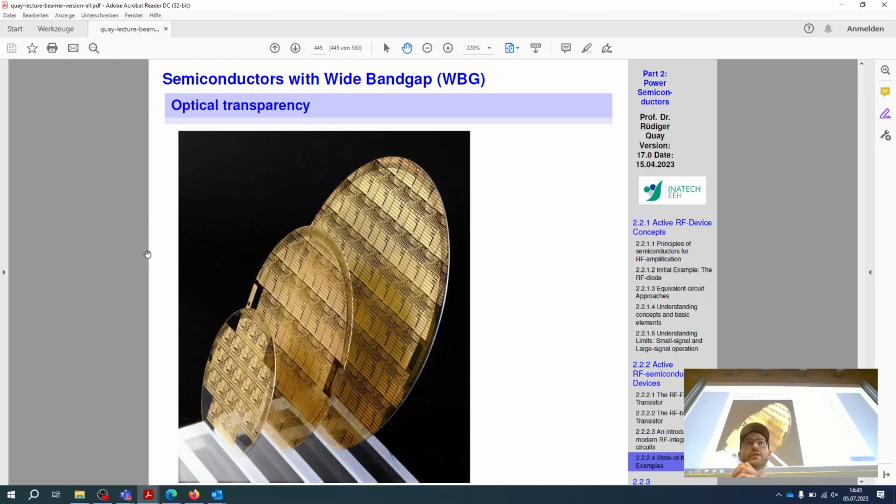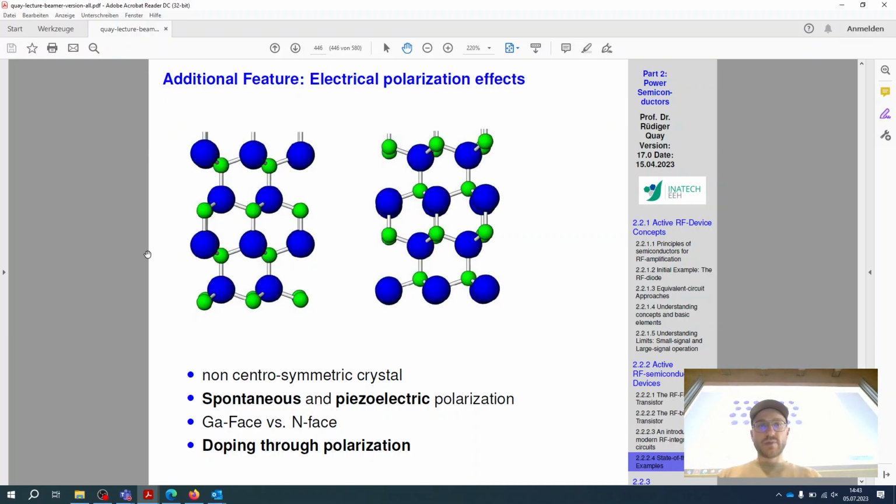Thus, the wafers are occasionally quite brittle. The physical properties of them are occasionally not as ideal in handling the wafers, in dicing them, in packaging them, and so forth. Thus, the packaging, the dicing, the handling, the processing of these wafers is far more involved than in the silicon world, just because silicon had so many years and so much push in money and interest to develop and to standardize the process.